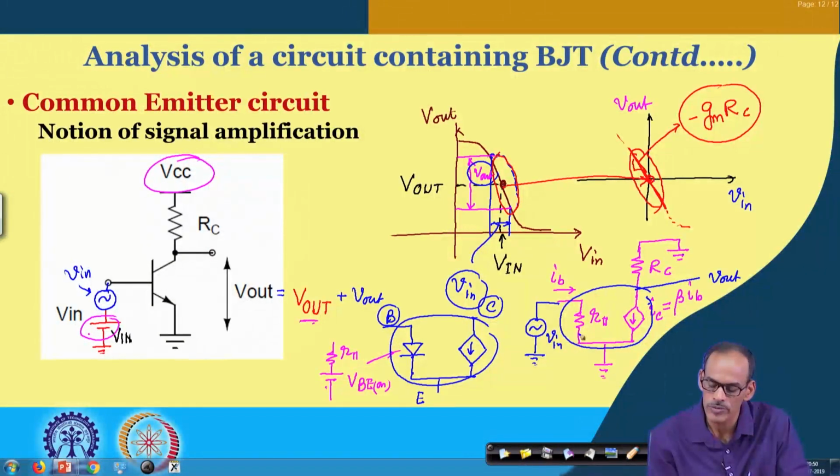Most importantly, since this characteristic curve goes through the origin, the input to output relationship is linear, and hence the superposition theorem can also be deployed with this simplification. The only thing is that we have to ensure that the Q point is not getting shifted.